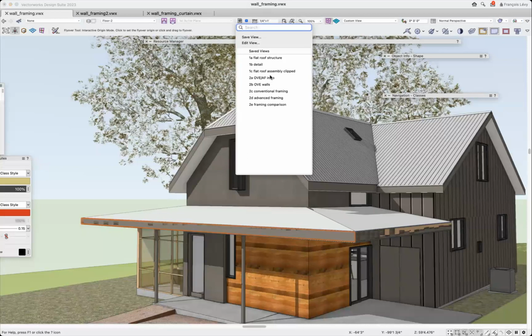Okay, so I think you can see the value in using the framing tool for this kind of detailing, as opposed to just doing a bunch of extrusions. Because with the framing tool, you can set the pitch as an angle, you can notch it, you can do some of the basic, dare I say, sort of carpentry tools like bird mouthing and so forth that you would do to a normal piece of lumber when you're framing. And you don't have to resort to just a bunch of extrusions.